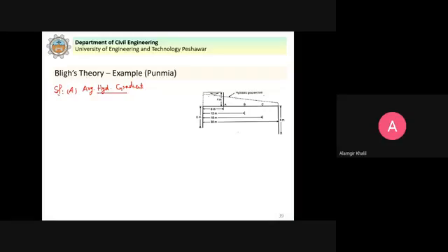So in order to calculate this, we will try to calculate the total creep length. So the total creep length in this case will be equal to L. What is that? We have this 6 meter because the water will start here, seepage, and then creeping along. Then it will come here again 6, 2 times 6. So 2 multiplied by 6.